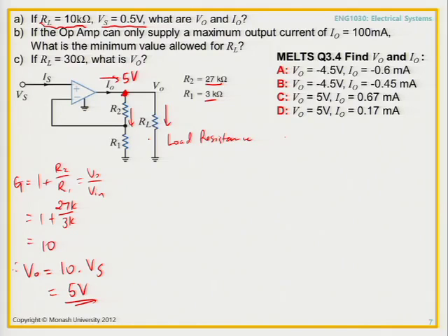We calculate R, which is 1 divided by 1 divided by R2 plus R1 plus 1 divided by RL. So you put these in parallel is what you're saying? Yes. You put these in parallel and you did V0 divided by, using Ohm's law, the parallel combination to get the current going through both branches at once. Perfect. It's one way to do it.